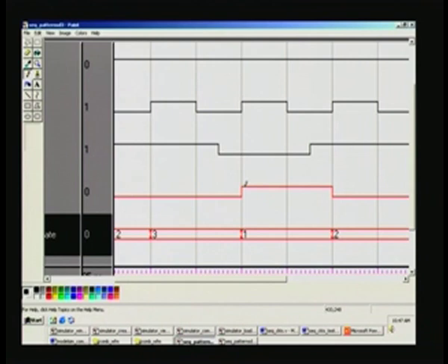Only then will it go into the next one, and only after touching this, although it is changing here, the processing actually takes place only at this point of time, as far as the output is concerned, because the output is also dependent upon the positive edge of the clock. Always at the positive edge of the clock in state S3, you set that particular output, right, it says here. That means it can take place only after 1 clock delay. Are you clear? It changes from state 3 to state 1 only when the input is 0, isn't it?